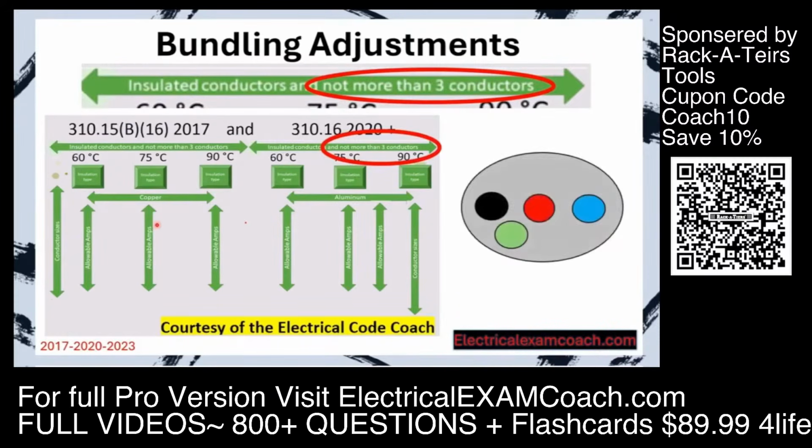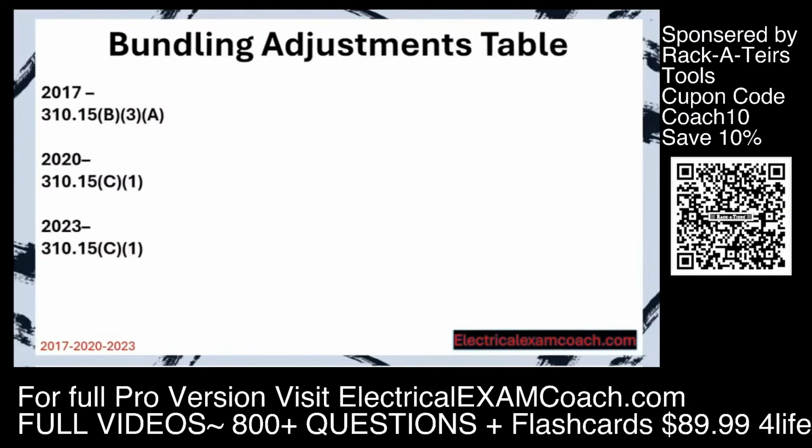Let's imagine that we have a piece of conduit here and we pulled in a black, red, blue, and an equipment grounding conductor. What this table is saying is that those ampacity values listed down below in this table are true as long as you have not more than 3 current carrying conductors in a cable, pipe, or raceway. If you do have more than that, then we have to do what's called a bundling adjustment. Let's learn about our bundling adjustment table.